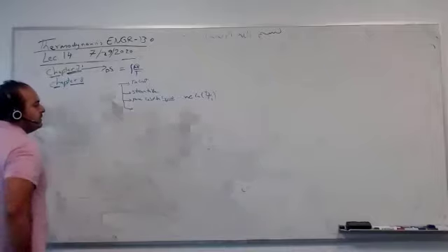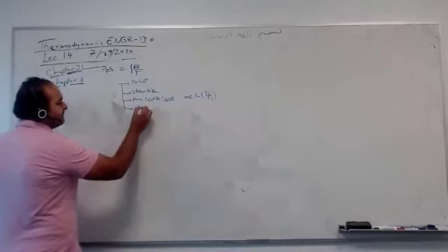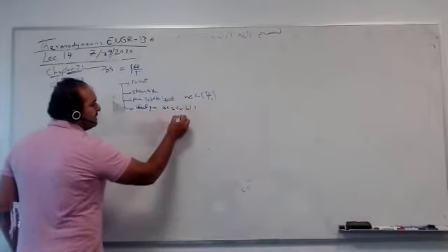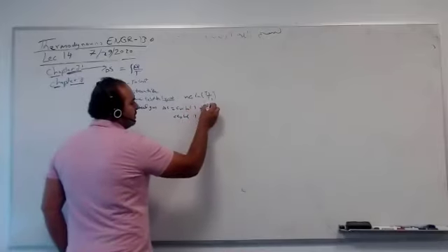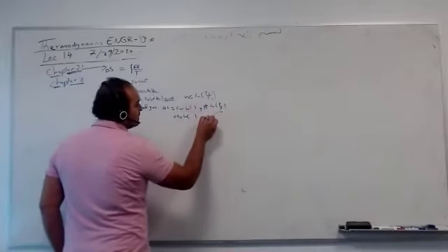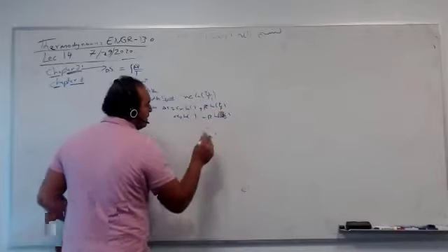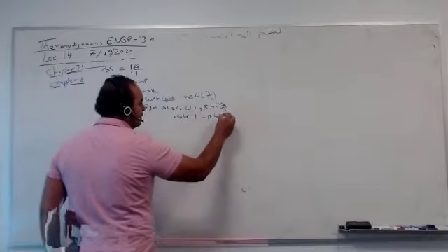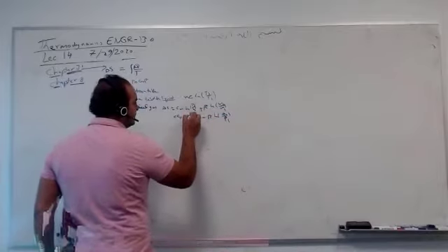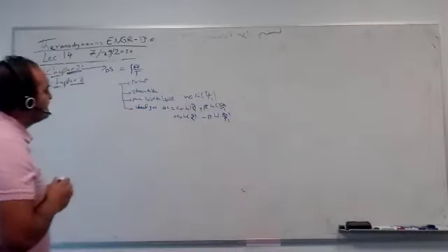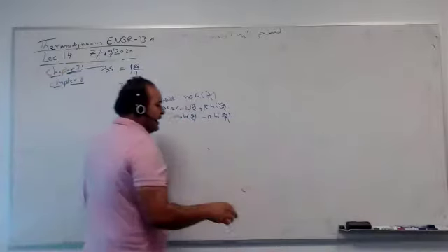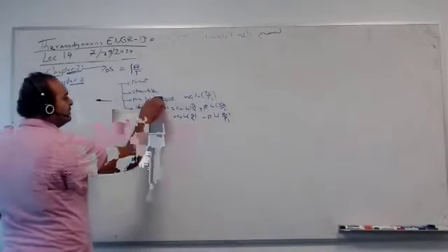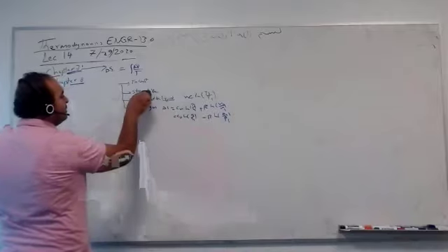And finally, we talk about ideal gas. So we have 2 correlations: Cv ln T2 over T1 plus R ln V2 over V1, and Cp ln T2 over T1 minus R ln P2 over P1, always 2 over 1. There are 4 cases for this, so you know which case you have, and you need to do it. For example, aluminium, pure water, gas, steam table, temperature constant.